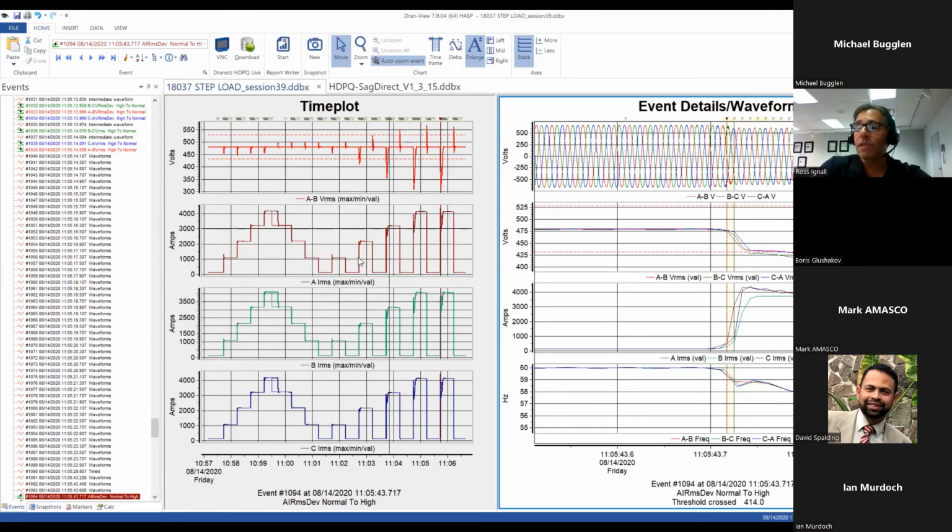Their intent is to look at what the impact and the response of the facility is. They're looking at the real loads on the output, usually of the UPS systems and all the power systems, to make sure they're behaving according to the system design and the manufacturer specifications. Here's the step loading in current for phases A, B, and C. Just as an example on phase A, I didn't want to crowd this too much. B and C are available, but they're not plotted here.